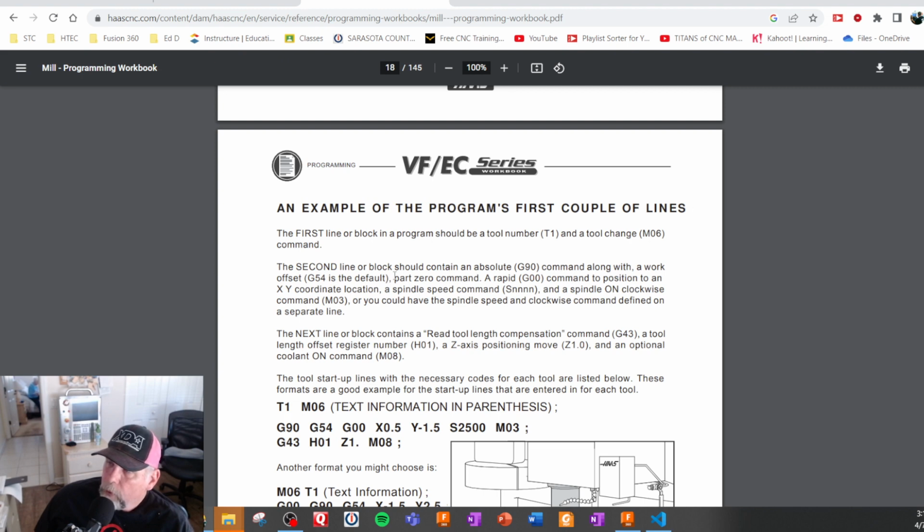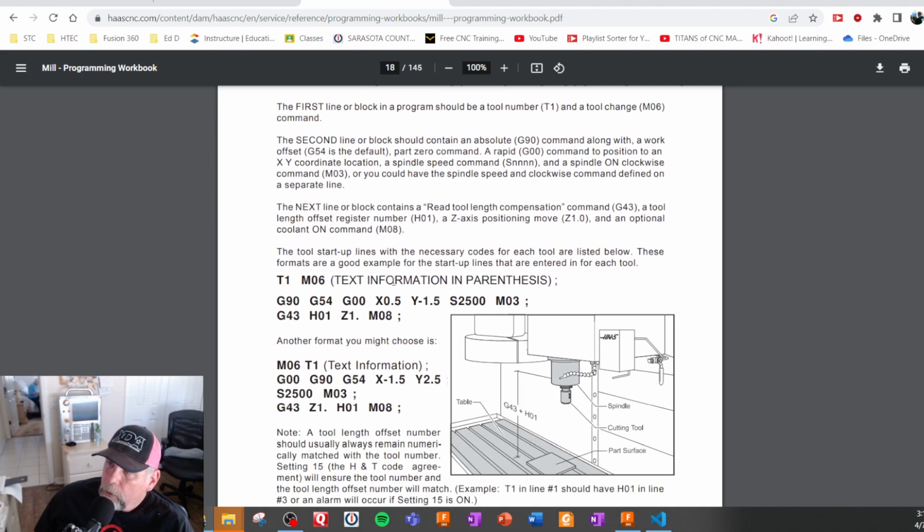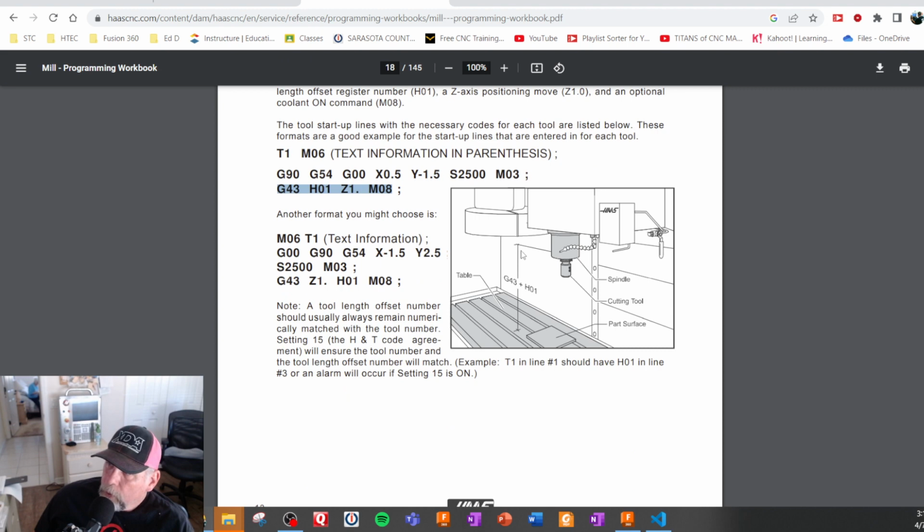Mark Terryberry has a very good video of that, the first 9 lines. Right there, we got tool change, we got the height offset command, all that stuff there. Height offset is incorporating this, like the tools are all different lengths. So you got your Z coordinate with the G54 command, but it has to add or subtract the height. That's where this comes in.